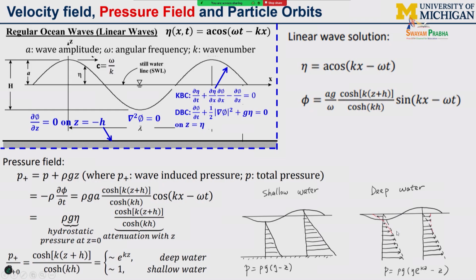For deep water, it's not a linear relationship. And you get a sense that we care about the dynamic pressure, which follows the same pattern as what we learned just now. If the water is at a quarter of a wavelength depth, the pressure has already decreased to 23%. Therefore, you just imagine it that way.